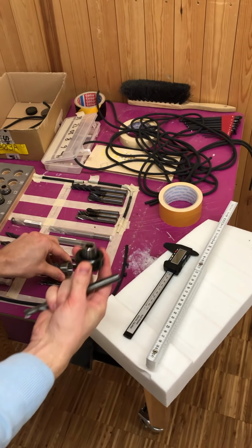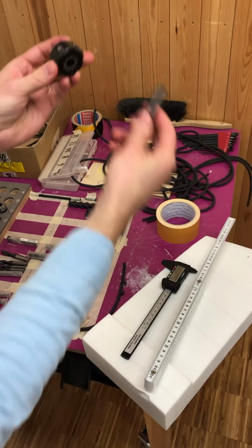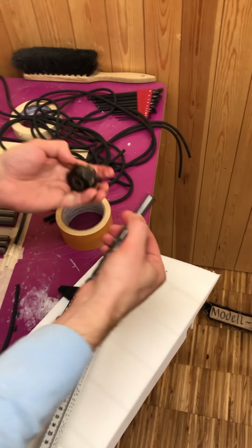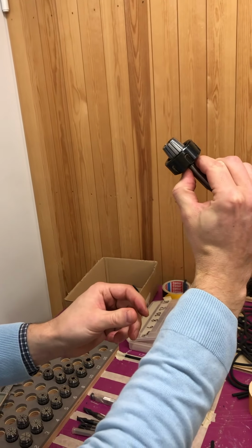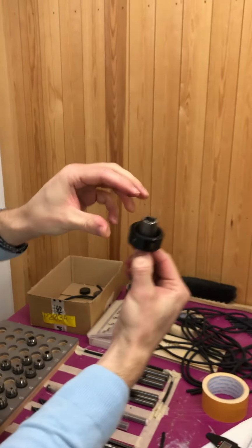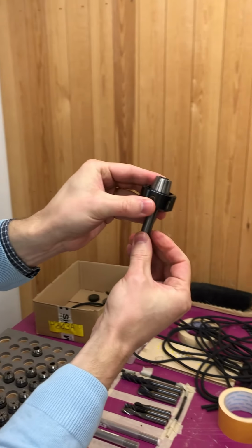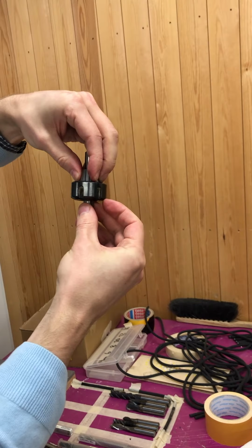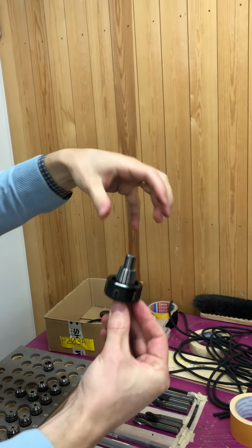But you can see here that if you insert it around 2.5 centimeters, then it is securely attached in the collet. The collet will produce a squeezing effect on it, but you will also hinder it from moving, because if you would insert it too far, then it can slide vertically when it collides, when it cuts the material.